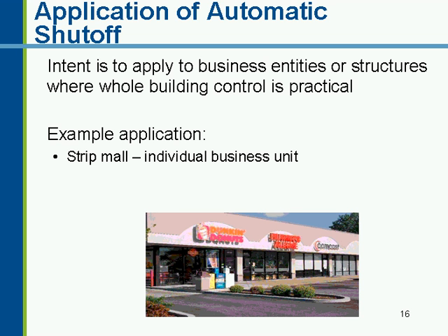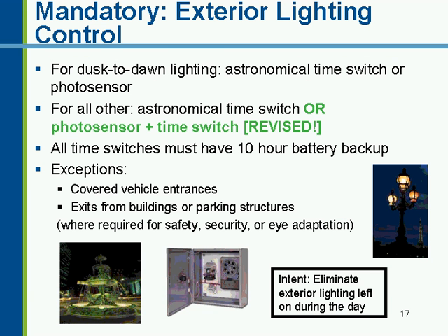So the actual language would say that an auto shutoff control is required here. But this really isn't practical in that each of these strip mall businesses might have different operating hours. So again, the intent is business entity or structure. So a strip mall with small units, if the unit is less than 5,000 square feet, will typically not have to have this requirement. Similar examples may be out there. This is just a good one to highlight that. So that pretty much covers the mandatory requirements for interior.